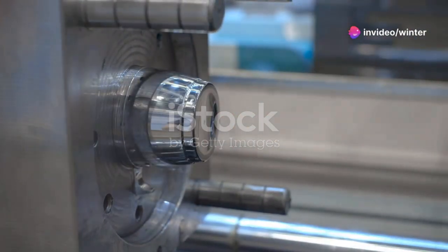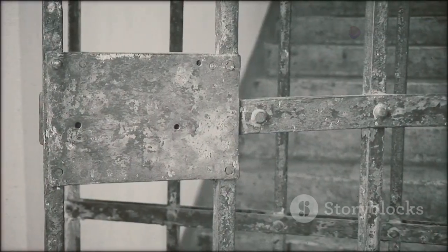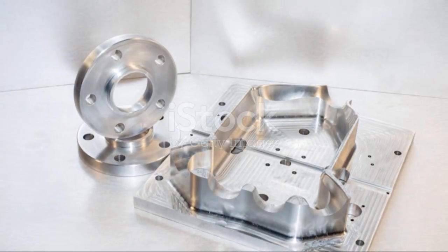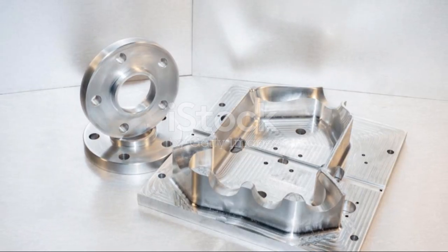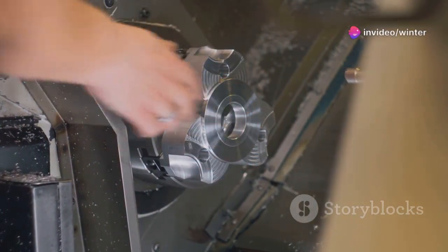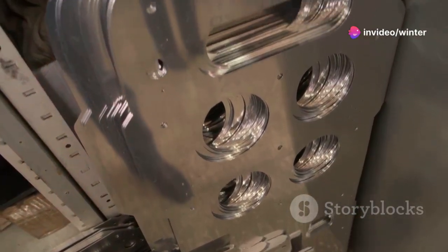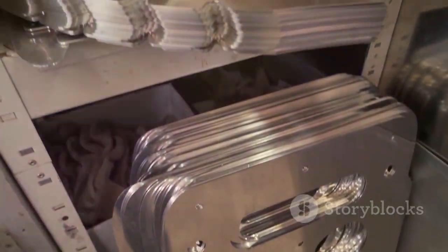Your mold isn't just a one-time investment, it's a long-term asset. High wear areas like gates and shutoffs will need maintenance. Design these as replaceable inserts, not part of the main mold block. When they wear out, swap them quickly. No need for expensive repairs or downtime. Modular inserts turn major repairs into routine maintenance.